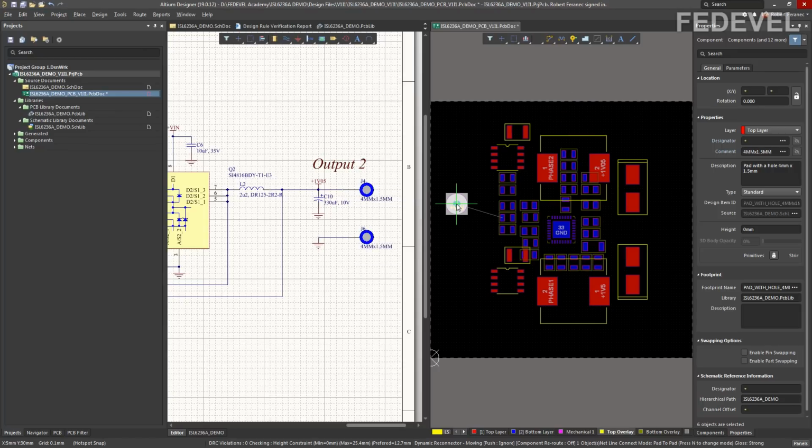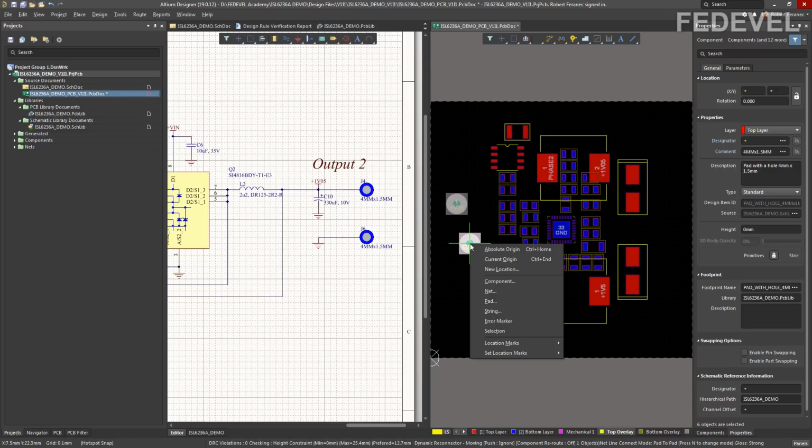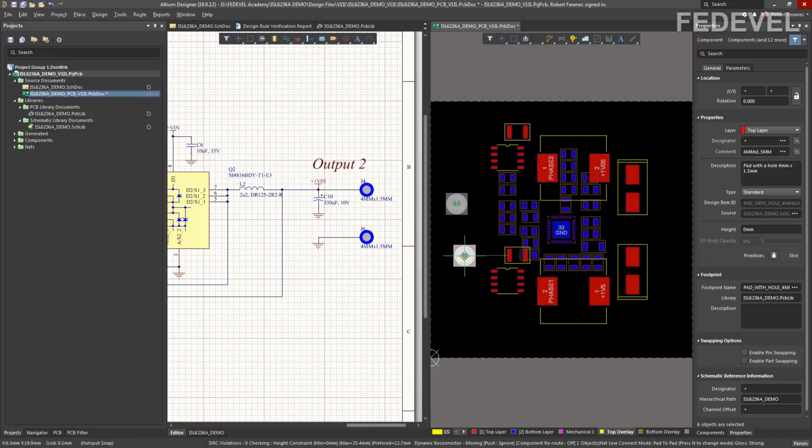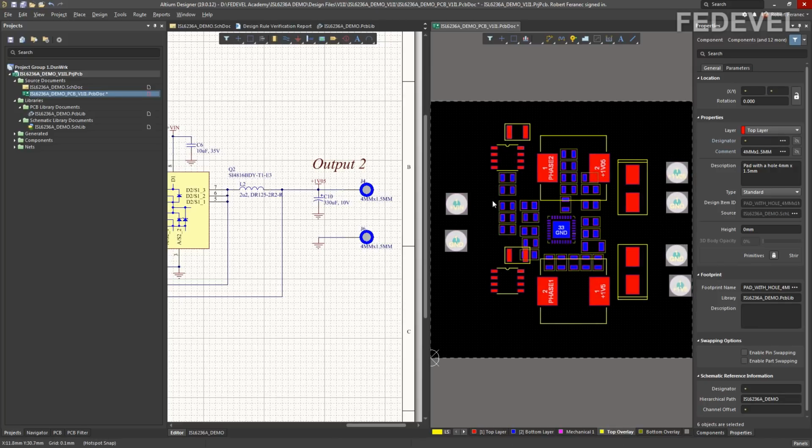Enter, and do not move your mouse, because right now your cursor is at the location that you specified, 5 by 30. Press left click on your mouse. Perfect. And if you like, you can use J again and do it through this menu, or a much faster way, we can simply place it approximately somewhere here and we will manually adjust the position of the components.